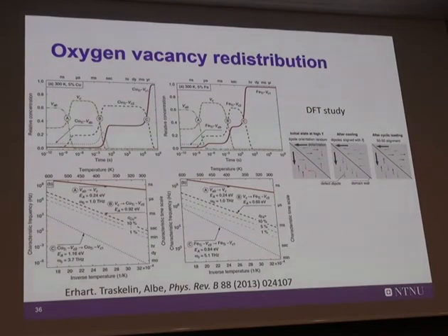Then you start the diffusion processes, and the dipoles are aligning with the polarization direction in the domain. This is a domain wall. So you see that all of these small green arrows are now pointing in the same direction of the internal polarization direction in each domain.